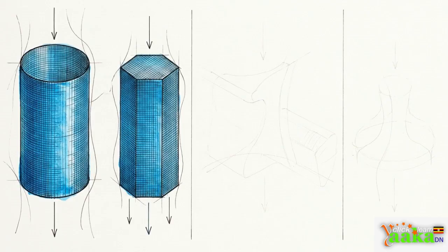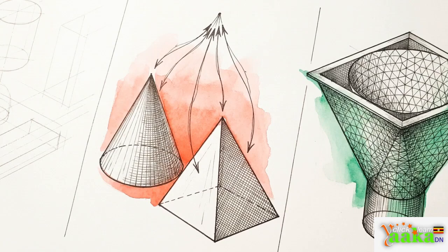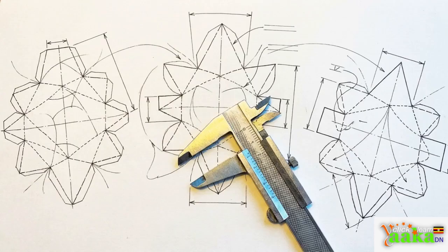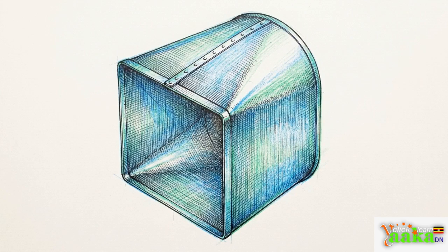This comparison table maps out exactly when to use each approach. Parallel line development is for constant profiles like prisms and cylinders. Radial line development is for single apex tapers like cones and pyramids. And triangulation handles the irregular transitions. By accurately matching the 3D shape to the correct development method, projecting your true lengths, and securing your practical workshop allowances, you ensure that your flat designs will ascend perfectly in the real world.